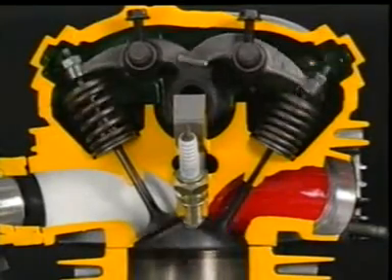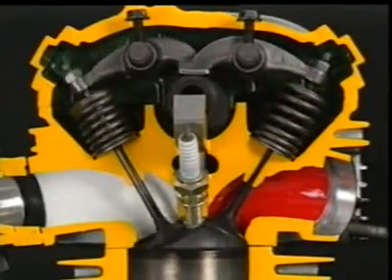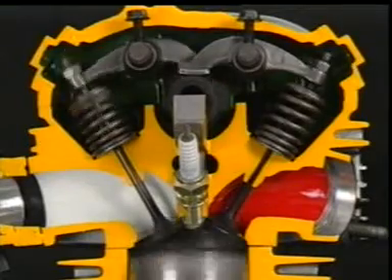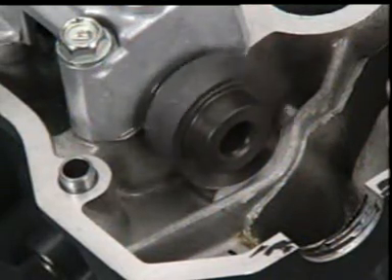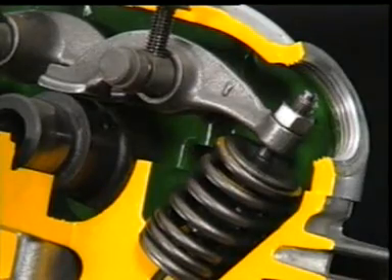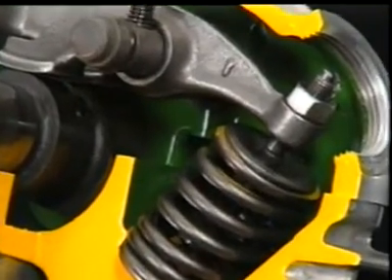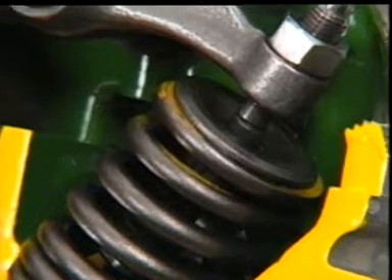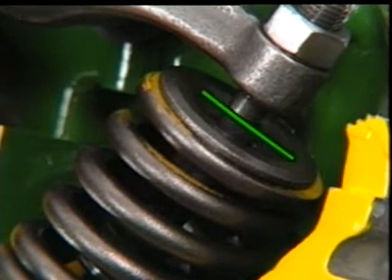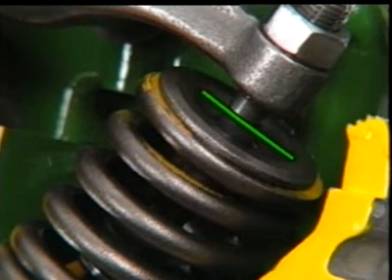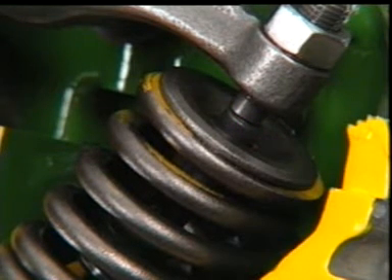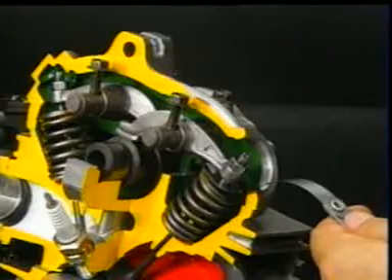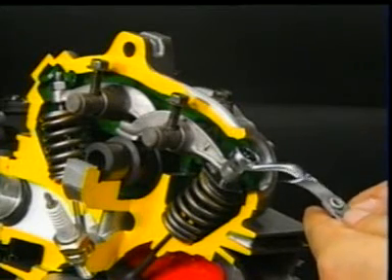The operation of the valves differs according to the type of 4-stroke engine. Some engines utilize a rocker arm between the cam and the valve tappet, and others have the tappets rest directly on the valves themselves. In both cases, there is always a gap between the valve and the rocker arm, or cam and tappet. If there were no gap, the valves would not close completely during the compression and combustion strokes. There would be leakage of fuel-air mixture, and the power output of the engine would be reduced.